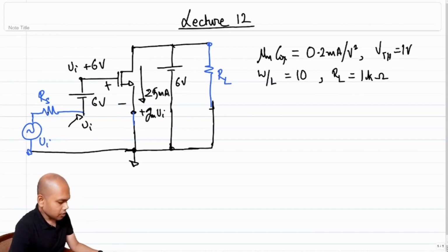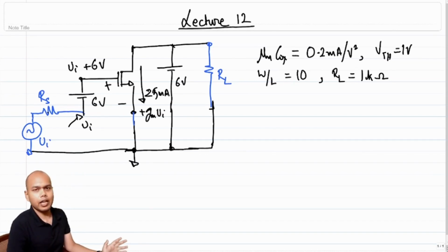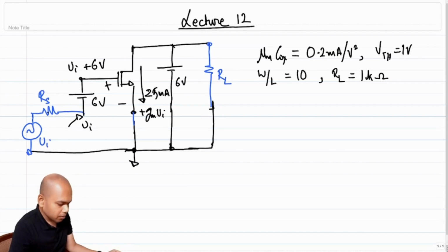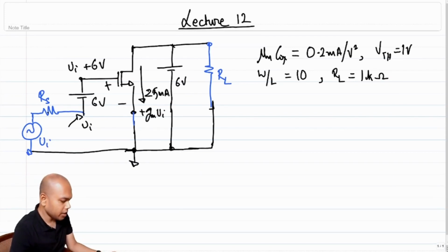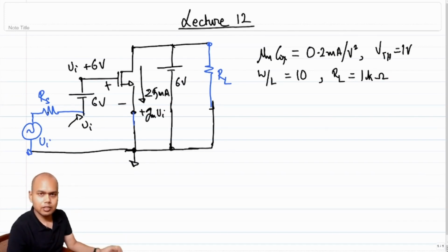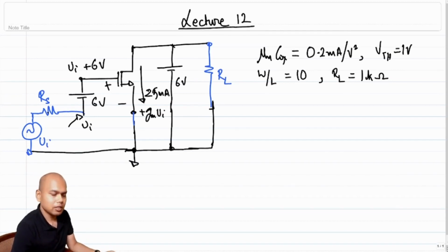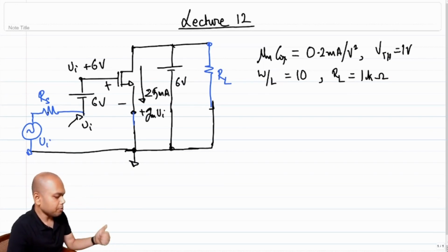We were halfway through, because under the given conditions, we want a gain of, let's say, 10 across a resistance RL of 1 kilo ohm. We saw that we required a Y21 or a GM of the transistor to be 10 millisiemens. From there we back calculated the required overdrive, that is the VGS-Q minus threshold voltage. From there we got the value of VGS in order to get a GM of 10 millisiemens, and that VGS came out to be 6 volts.